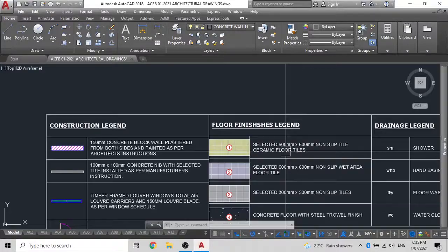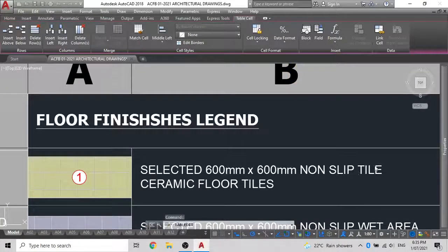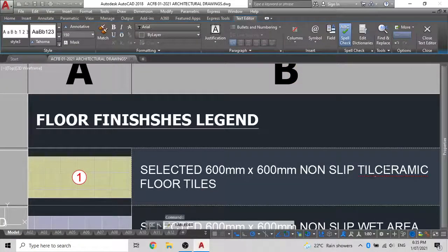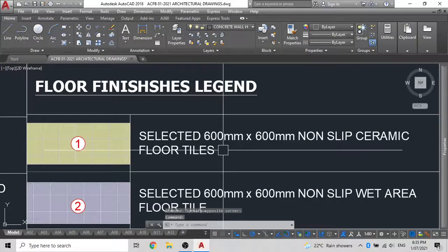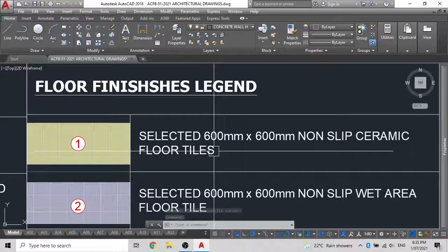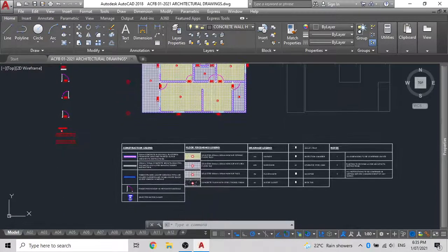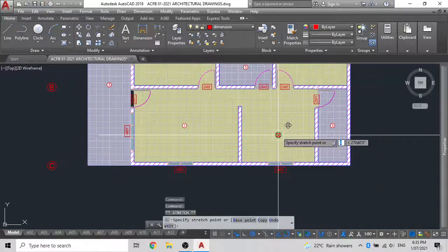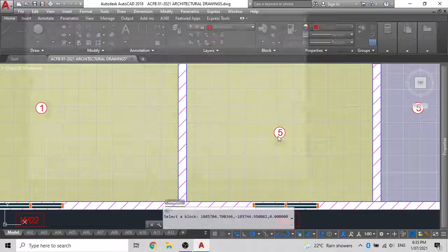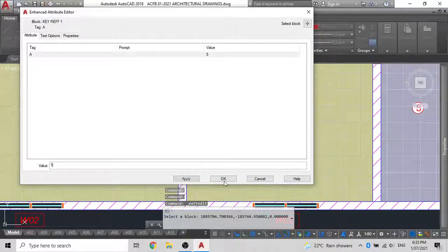ceramic floor tiles. Now that's a typo. So what you can do is just delete the tile. And there you go. Now there are several square meter rates that we can also enter here. So since this is an expensive range that I'm using, I'll use a $75 per square meter VIP insulation, adhesive, and everything else in the tile trims and all. So I'm using the expensive kind here. And what you can do is just go ahead and change everything like so.